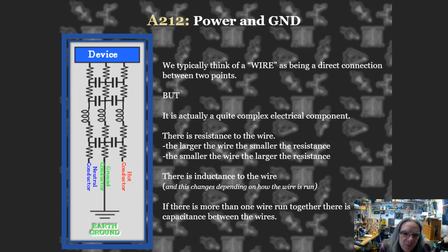So up until this point, we've thought about connections on a schematic. If we have two different points on a schematic, both connected to ground, we've thought of those as being the same voltage. So we think of them as being the same point on the schematic, the same net, the same voltage, all those meaning the same thing. No matter what side of the schematic they're on, complete page, separate page even of a schematic, we can name them the same thing and they are the same point and they have the same voltage. That's what we've thought of so far.